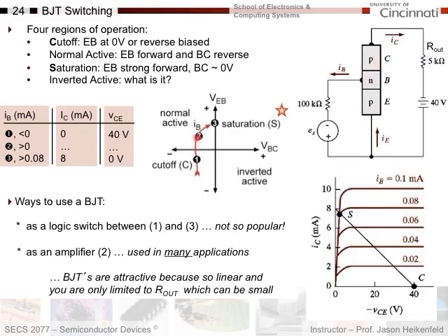Well, look what happens here. I'm increasing VEB, and now this curve pulls VBC down to 0. That's why it goes to here, because it's VBC pulled to 0. That makes sense, because if all the voltage drop in saturation is across the output resistor, then the voltage drop across here goes to 0, keep increasing VEB and IB, and that pulls VBC down to 0.